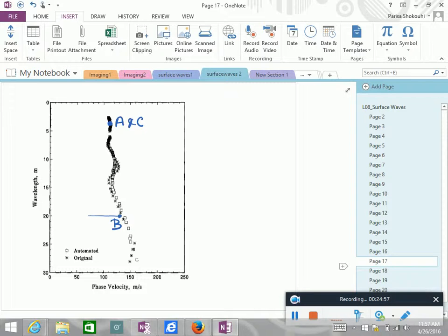And I told you that the distance between the source and the first receiver is typically equal to the distance between two receivers. That means that you need to repeat the test for different spacings, and then you put all the data points together to get a dispersion curve through the procedure that I showed you. So now, what is the question?